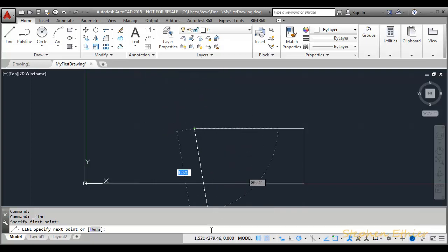Let's right-click on it and change it to absolute. Move your cursor back up till it reaches the 135-degree mark, and then you look back down onto the status bar, and you can see it's giving us the absolute X and Y location of that point. We want that line to be at 1, 2.